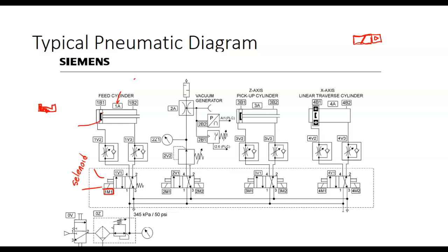Actuator number 2 is a Venturi converter, so it's not a true actuator, but since it's the last thing on the chain, they give it an A. It converts a flow into a vacuum. We can adjust it. It's got an adjustable pressure switch on it, or pressure sensor, excuse me, that we can set when it gives us a true or a false.